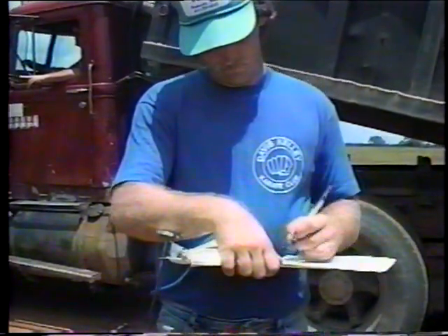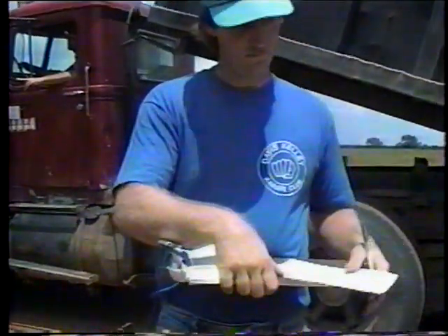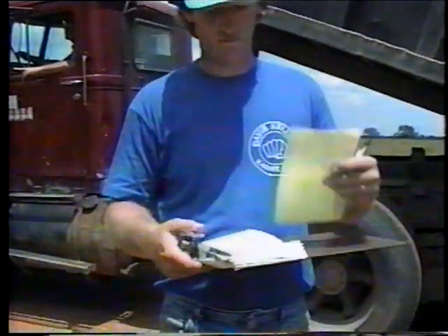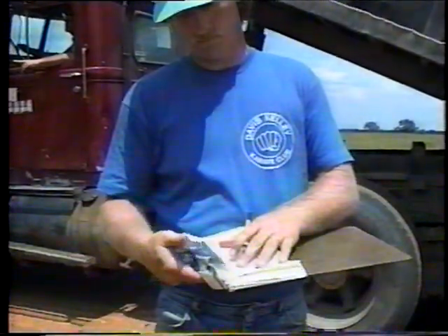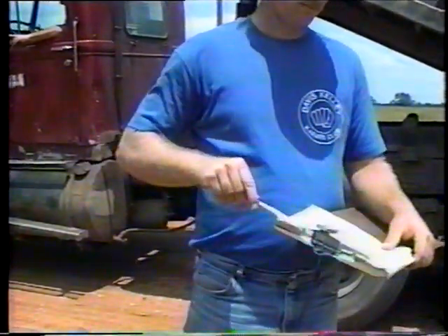You should also compare the gross vehicle weight with the weight shown on the delivery ticket to be sure that the trucks are not overloaded. Some agencies require you to reject overloaded trucks. Check the contract documents to be sure.